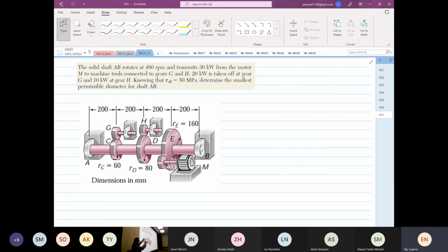Okay. Why? Because you need knowledge like this to go into transmission shafts. And if you look at a transmission shaft like this, right, there is no axial loading at all. Most of the time, not all the time, most of the time, we don't have axial loading. Okay, I know there's 2 students out there saying, yeah, we are seeing that now, right? There's no axial loading. Okay, so this set of equations that I've written down has no axial loading abilities. Okay, remember that. If I were to give you a problem that's axial load, you cannot use these equations anymore. Clear? Okay.